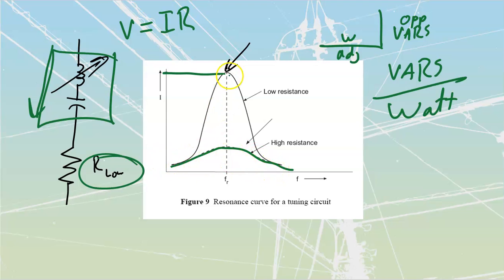If I want maximum signal, I want to have a minimum amount of resistance so that I'm able to have maximum current at that specific frequency. We'll cover these tuned circuits a little bit later on when we go through some electronic stuff. Particularly where we're going to see this series resonance being critical is when we get to filtering in third year. You will probably have forgotten about this because who bothers remembering anything from previous years when you come back to apprenticeship schooling, but just don't be that apprentice.